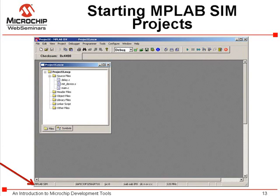MPLAB deals with applications as projects. Projects are the source files that are used to build the application, along with compilers, assemblers, and linkers. In this project are three files, main.c, delay.c, and an assembly file, int_devices.s. All will be compiled using the MPLAB C compiler and its tool suite for the dsPIC family of digital signal controllers. But this process is the same for the other families of Microchip microprocessors. For more information on setting up a project, see the Introduction to MPLAB seminar referenced earlier.